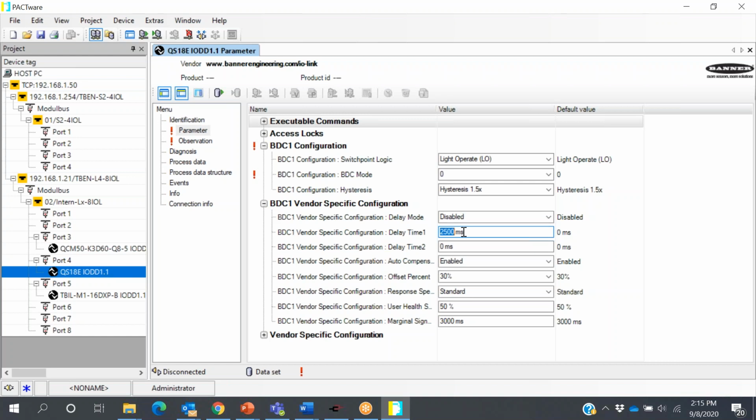Another great example is this is a temperature transmitter and a temperature switch. So it's got a 4 to 20 milliamp output, it's got a PNP switch point output, and it has IO link. But again, I'm not ready to deploy IO link into my control architecture. I just want to take advantage of it as a configuration tool. This will come from the factory with 4 to 20 milliamps scaled at 0 to 150 degrees C. Well, I might have 4 different applications in my facility, and I want them all to be scaled differently, and I don't want to have to purchase something expensive or purchase 4 different part numbers.